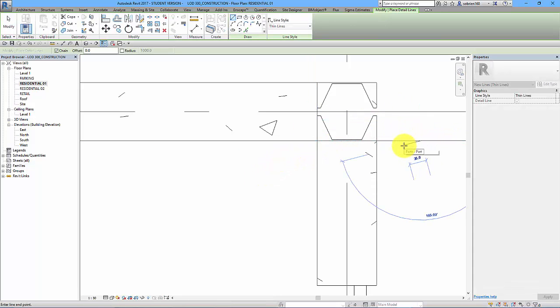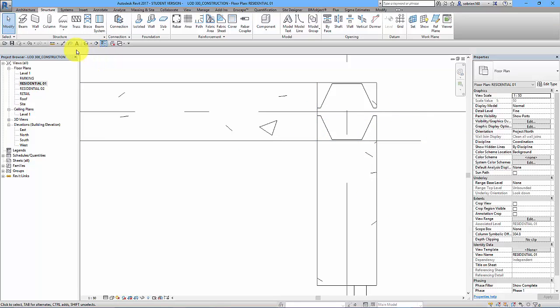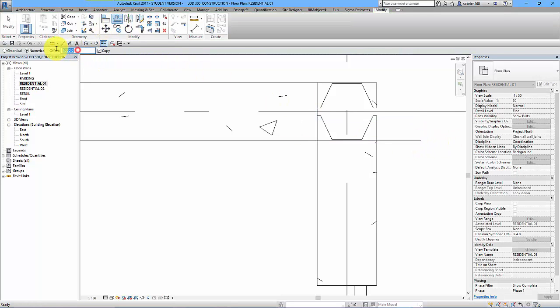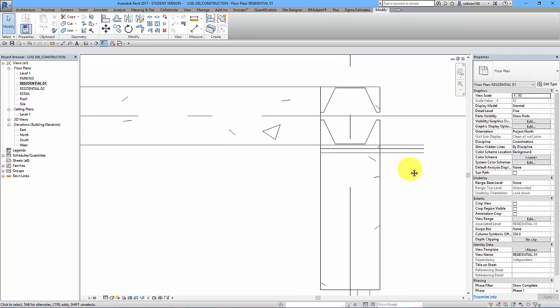and draw it across. Whoops. And I'm going to offset that detail line by 16mm, just so we have some kind of a guideline as to where we want it to be. So now we know where we want it to be. And let's just be extremely accurate, let's offset it again, and this time I'm just going to offset it 8mm, so we get one in the center there. So now I've got a position for a cut.